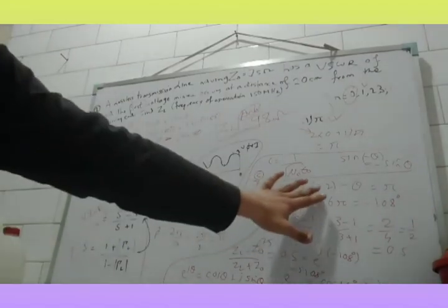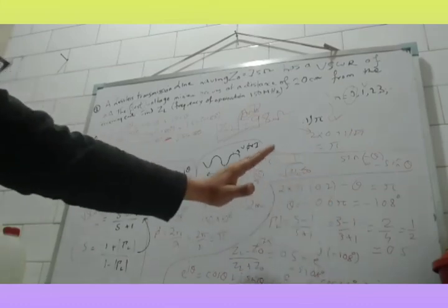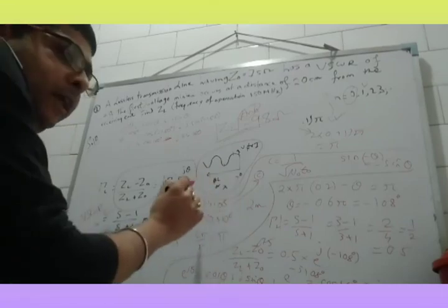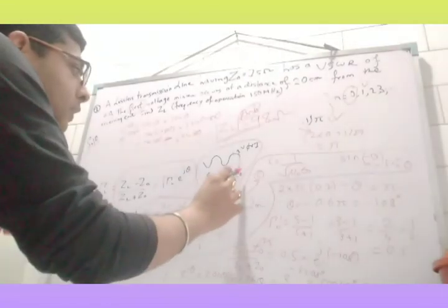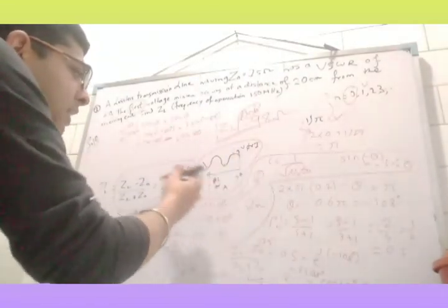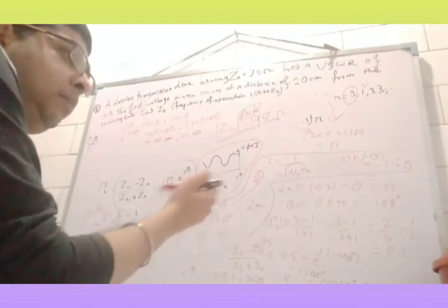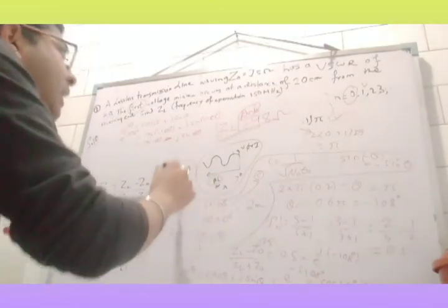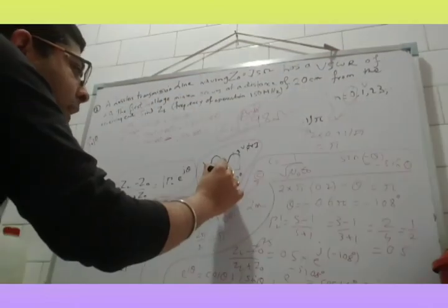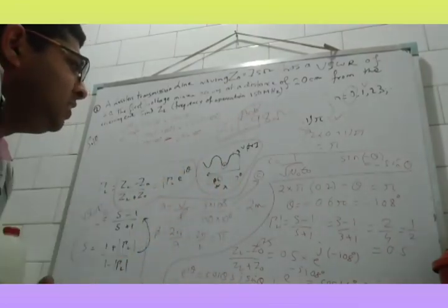Okay, so one thing: this formula, this X what we have put, is basically calculated for the load end. So if this is my load end, say this is the voltage axis, this is the length, so electrical length you can say beta L. Voltage minima means this, the minimum voltage.